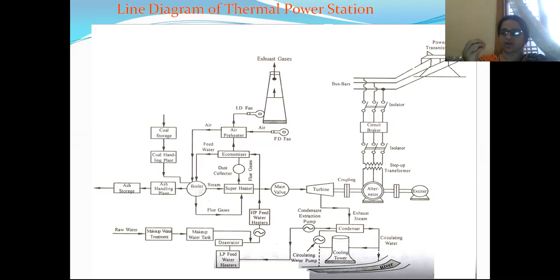There are even artificial cooling towers. Natural fans or artificially induced fans will reduce the temperature of the cooling water, which will be passed around the exhaust steam in the condenser.